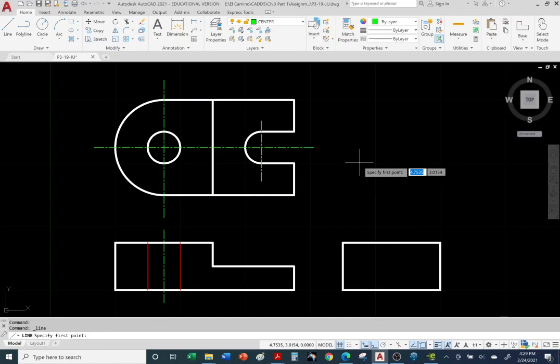See, I can type in lengths. I can type in angles, right? I can type in coordinates. I can just click and see how it's waiting for me to type in a length or an angle. Let's say I wanted a length of 1 unit, and then I can hit tab and change the angle. It's waiting for me to type in an angle. Let's say I type in 45 degrees and tab. There it is. So this is dynamic input.